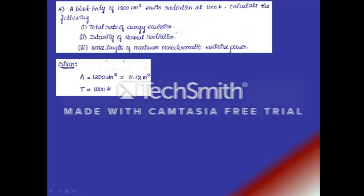So let us try to understand the problem. The first thing in radiation heat transfer is to find out the type of the body or given surface, whether it is a black body or gray body. This problem says the given body is a black body, so you are free to use all the formulae applicable to a black body. The area of the body is given as 1200 square centimeter. Convert that into meter square, so it is 0.12 meter square. The temperature of the black body is given as 1000 Kelvin.